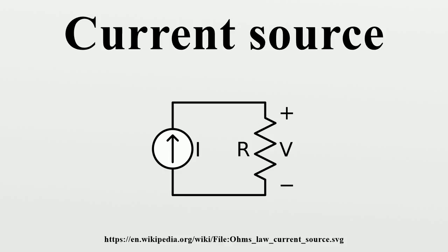As a result, the total current flowing through the load is constant and the circuit impedance seen by the input source is increased. However, the Howland current source isn't widely used because it requires the four resistors to be perfectly matched, and its impedance drops at high frequencies. The grounded load is an advantage of this circuit solution.